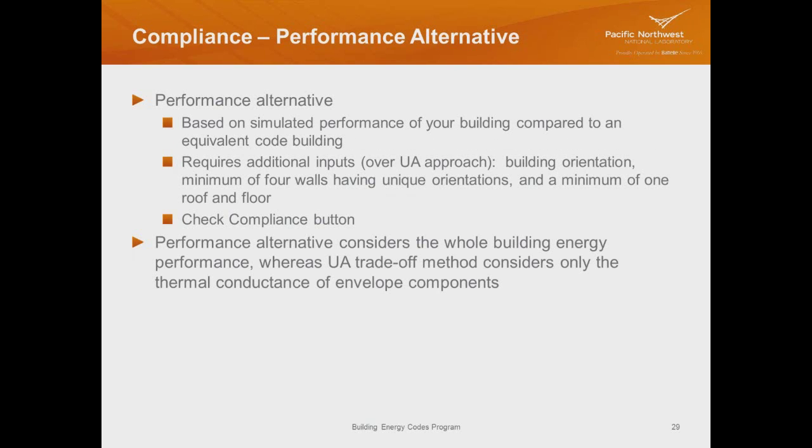There's also a performance alternative in REScheck. Now, I talked a little bit about whole building performance, and this is not a whole building performance tool, but it does have a simulated performance approach. And really what that is, it looks at your solar gains, and it can look at your mechanical equipment. It will do like for like on mechanical equipment, though. You're not getting trade-offs for mechanical equipment. But it will look at the efficiency of the equipment and the solar gains on your building.